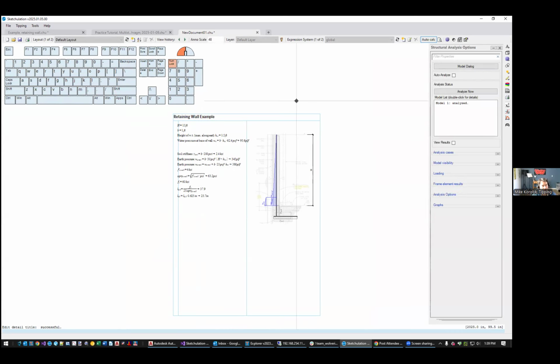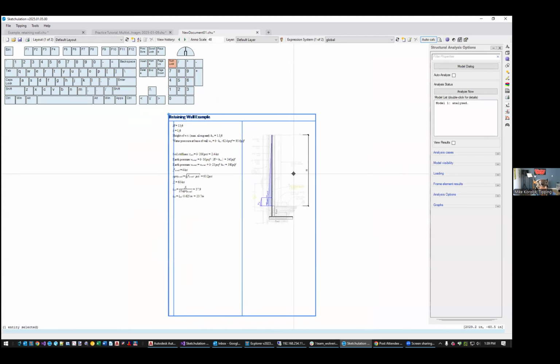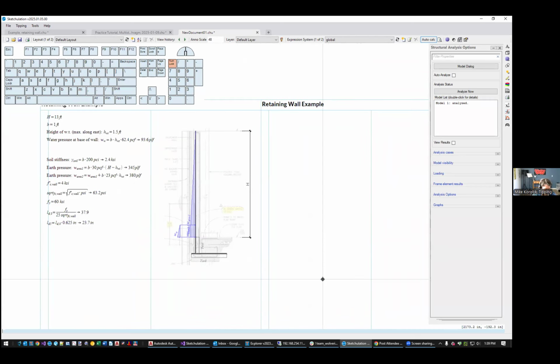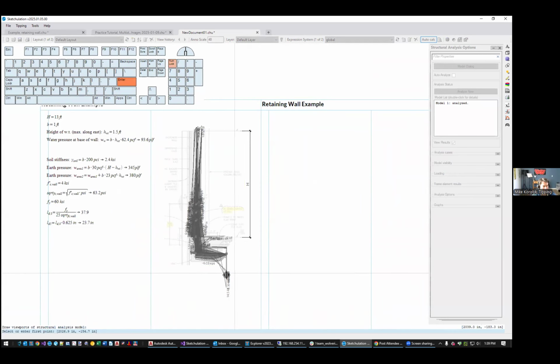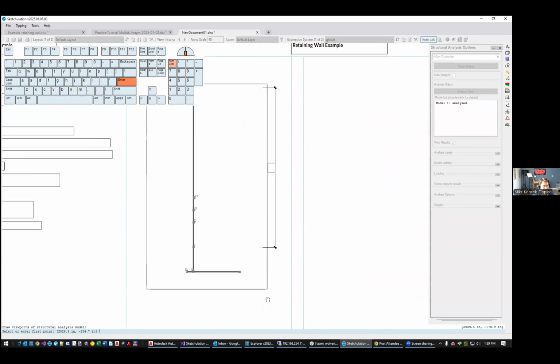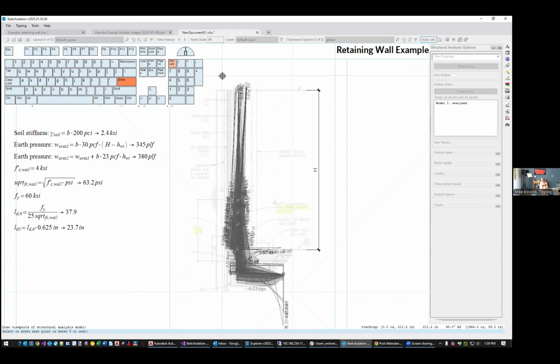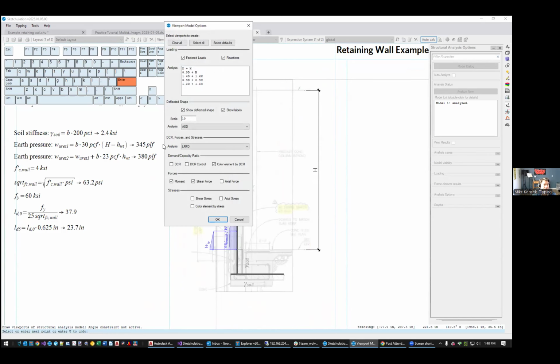Okay. And then I will click on this and I'll do an add page. Add makes my new page here. And then I'll do the viewport model command, VPM, this, and it shows all of the results on top of each other like that. So I can kind of see. I'm going to guess that probably my viewports will be good enough if I go about like that size, let's say, and decide what I want to show.